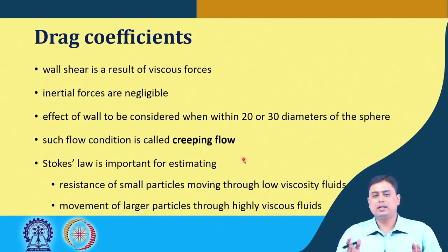If the walls are separated by more than 30 d or 20 d, we can say that it is an infinite pool of liquid with respect to that particle, and then Stokes law is typically applicable. If not, then the effect of the wall has to be considered and certain modifications need to be made in the Stokes law to calculate the drag force on the particle.